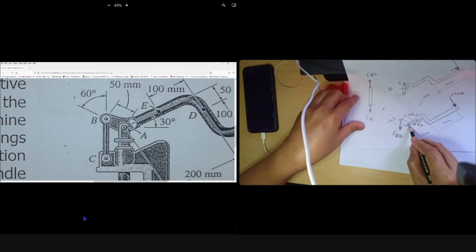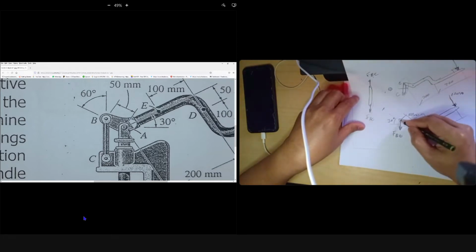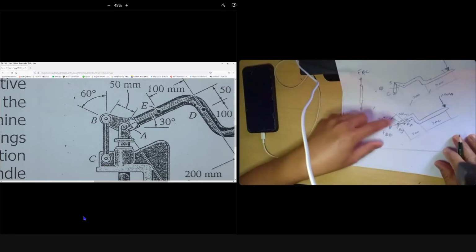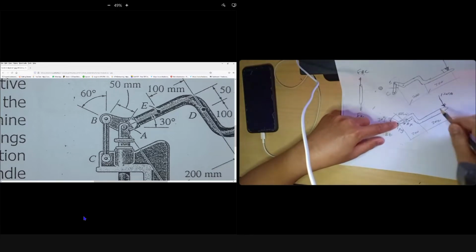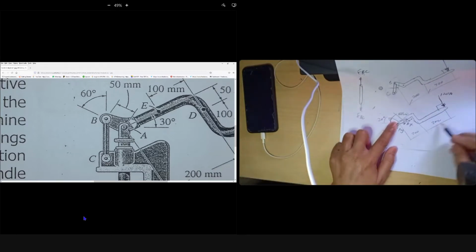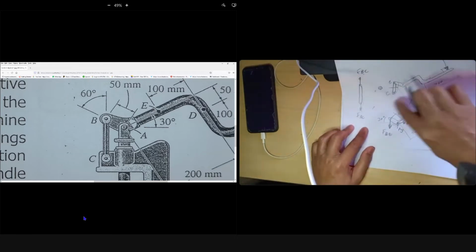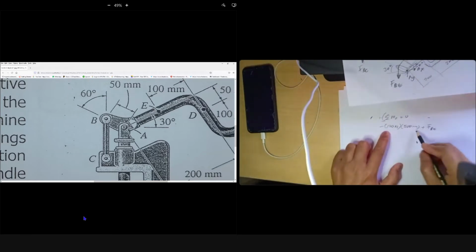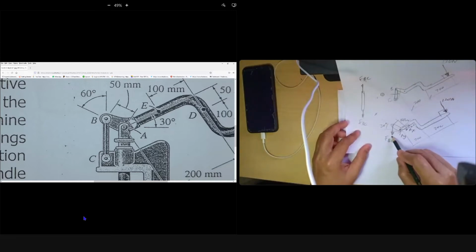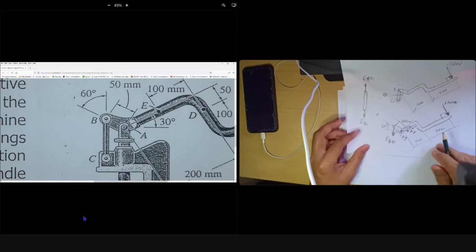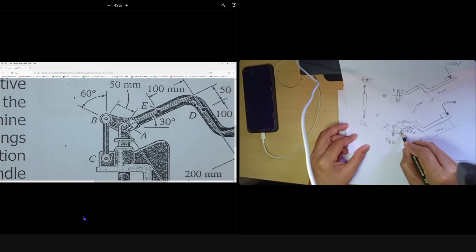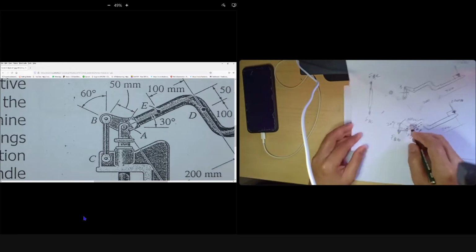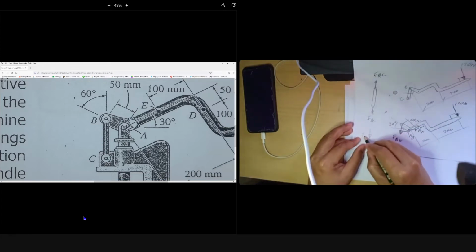Why the distance? The distance is horizontal because this force is downward, right? So what is this 120 Newton? We take it because it is perpendicular to the 200, 300. So 120 times 500, that one produces negative moment at A. What about this FBC? Times 50 or times 50 cos 30 degree? Because it's straight down. The distance is horizontal, right? Perpendicular to your force. Remember, guys, FBC.